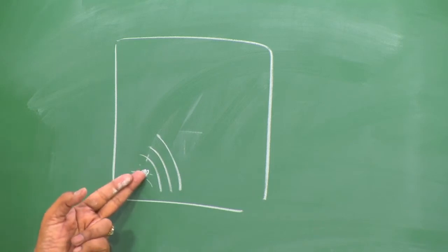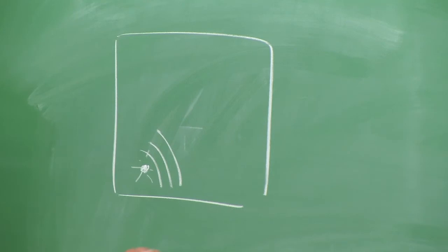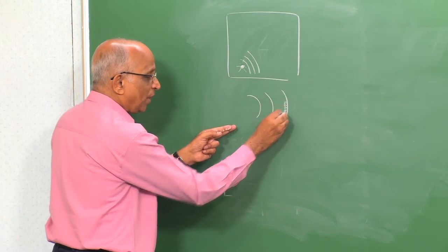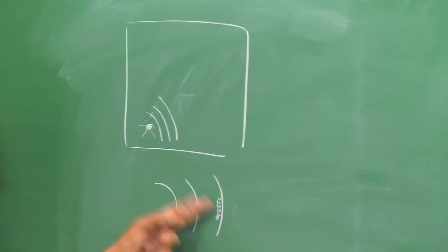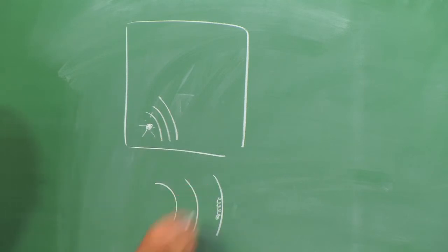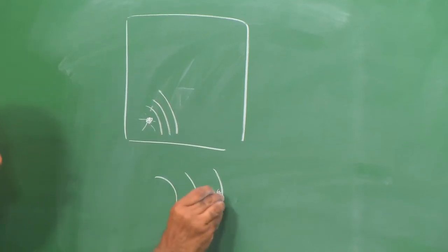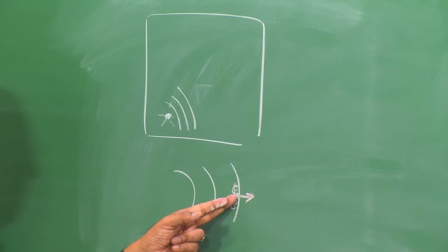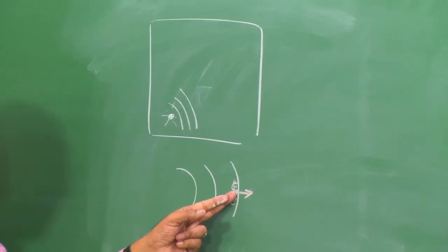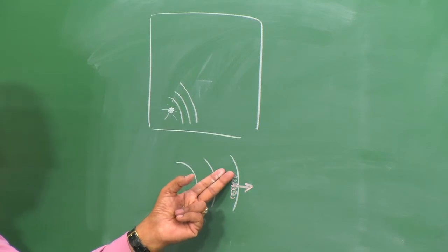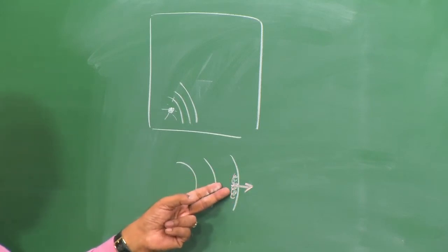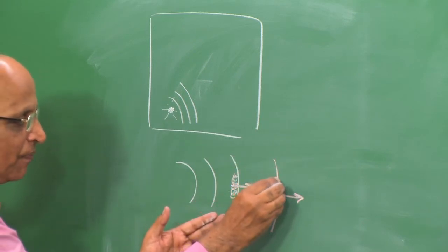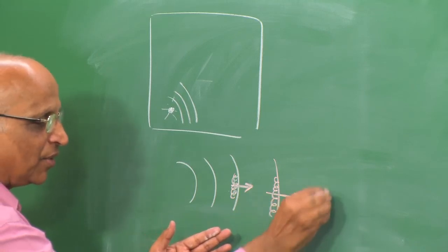But if the energy release is somewhat fast, sort of instantaneous, a shock wave could be formed, and behind a shock wave the temperature is quite large. If the temperature is quite large and it is an explosive gas mixture, the chemical energy which is released behind the shock wave could drive the shock wave, such that now you get a shock wave driven by chemical reactions. If the chemical energy release is such that it can overcome the work done during expansion of the gases behind the shock wave, I can make the shock wave travel at a constant speed, and this type of wave is spoken of as a detonation wave.